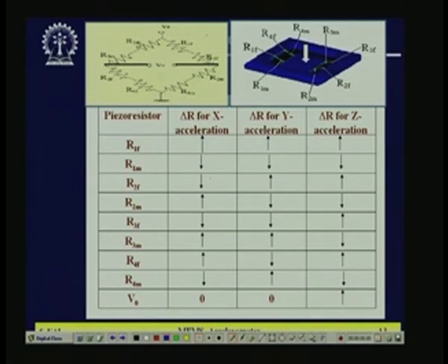If it is 1.5 kilo ohm per resistance, here 3, 3, 3, 3, so the bridge is perfectly balanced. Okay. Now if you go for acceleration, for example z axis acceleration, the proof mass will take this shape.